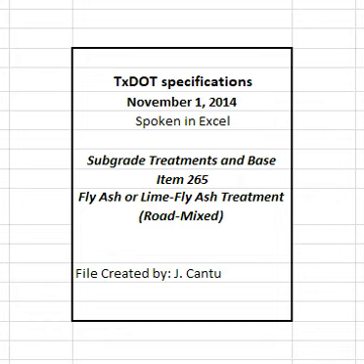When FA is furnished in trucks, the weight of FA will be determined on certified scales, or the contractor must provide a set of standard platform truck scales at a location approved by the engineer. Scales must conform to the requirements of Item 520, Weighing and Measuring Equipment. When fly ash is furnished in bags, each bag must indicate the manufacturer's certified weight. Bags varying more than 5% from that weight may be rejected. The average weight of bags in any shipment, as determined by weighing 10 bags taken at random, must be at least the manufacturer's certified weight.